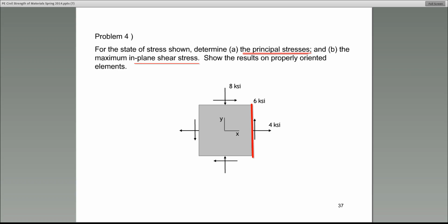All right, guys. The x-coordinate of that point is this 4 ksi. Do you see that? So the x-coordinate of the point on the circle that corresponds to that red vertical face is 4. Now, Helen, tell me, would that be positive 4 or a negative 4? You're absolutely right. It's a positive 4. Why? Because, look at it. The stress that we show is pulling away from the face. You see the arrowhead? So the x-coordinate is plus 4.